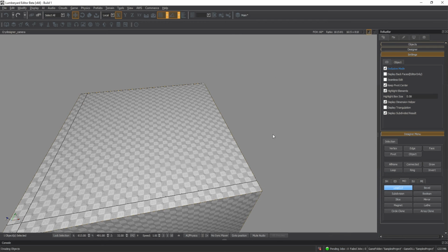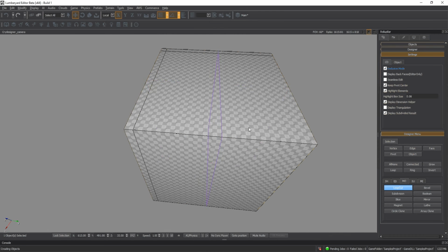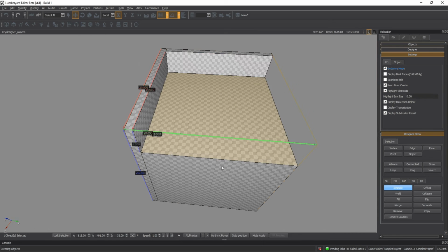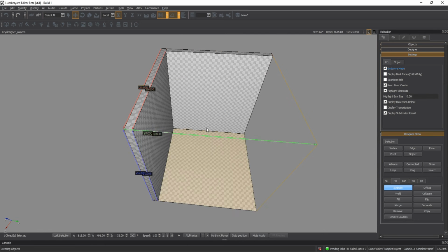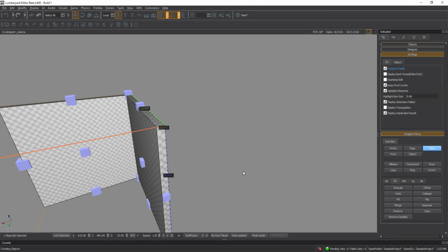So now I've got this nice little corner here that we can actually start to do something with. But how do I get rid of this whole bit over here? You could delete it and then append. That is one way. The way that I found is most efficient is to go to extrude, select the face, and just push it all the way to the bottom, and it just gets rid of it for you. That's so cool. Boom. Now we have this nice little corner.